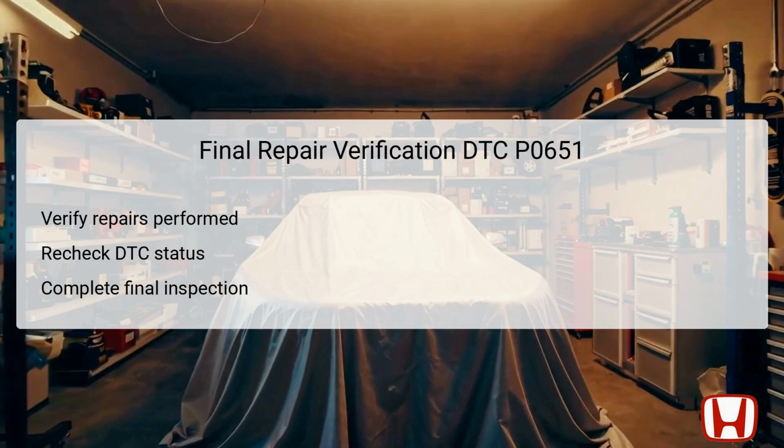Once repairs are completed, it is crucial to verify the effectiveness of the completed work. Begin by rechecking the DTC status using the HDS to ensure that the P0651 code has been cleared and does not reappear. This final check confirms that the root cause of the circuit malfunction has been addressed.